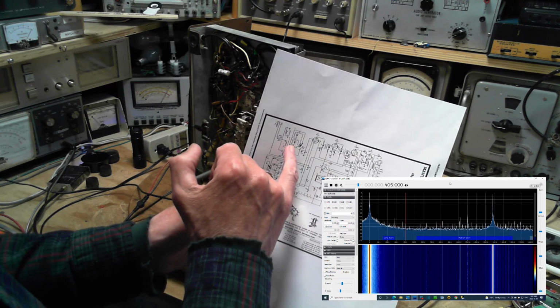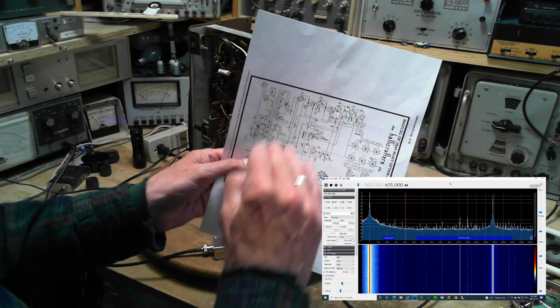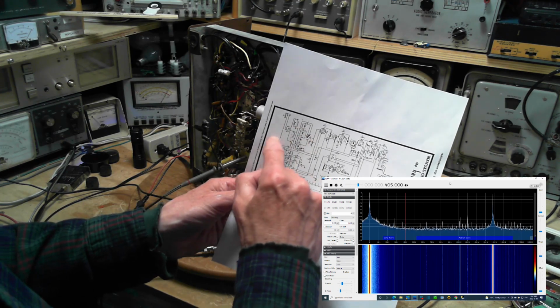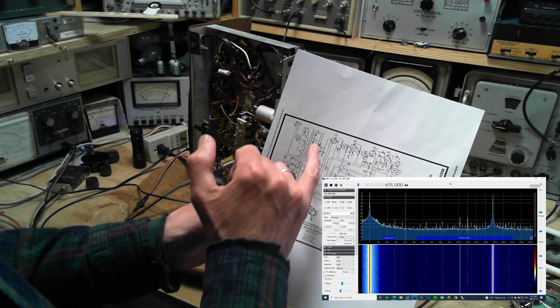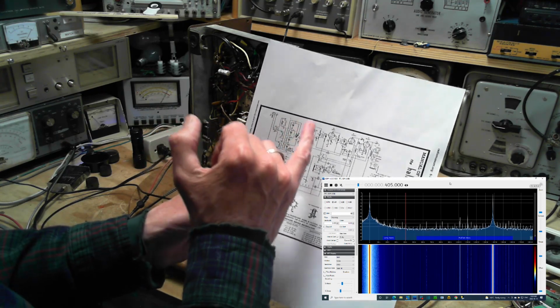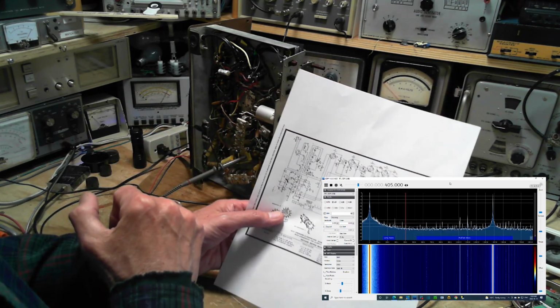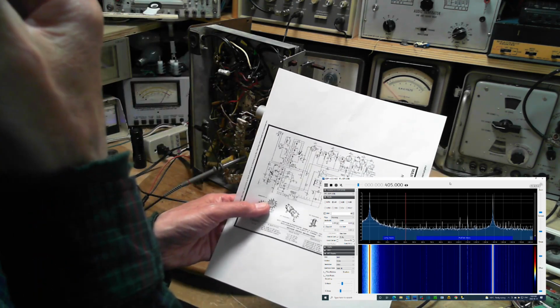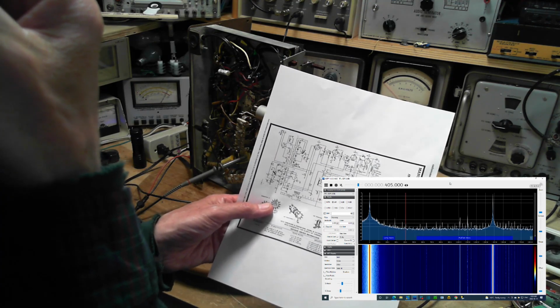If you're outside of that resonance, your signal is weakened. You have to go quite a ways though, because it's just one set of tuned coils. I think if you put an RF tube here, you get tuned coils, RF tube, tuned coils, then mixer. And that's really the advantage: 2 sets of tuned coils instead of 1.